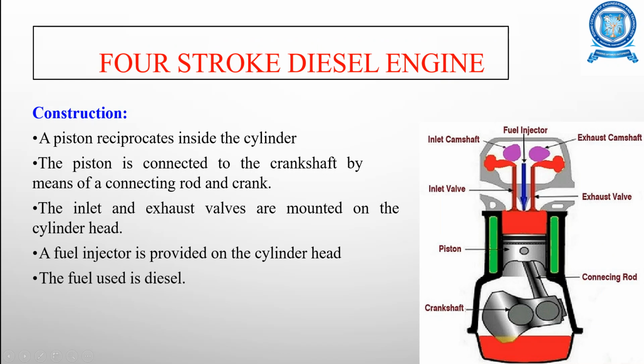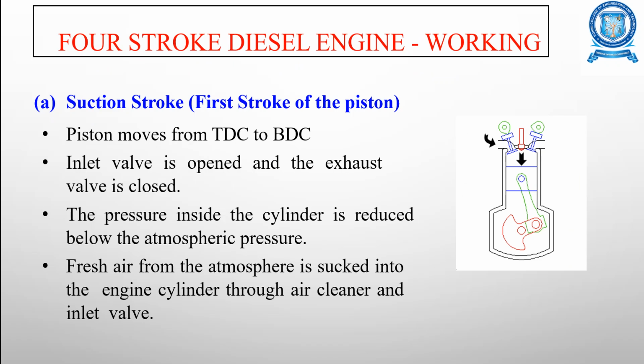In the four-stroke diesel engine, the fuel used is diesel, and this is the first stroke, that is the suction stroke. In the first stroke, the piston moves from the top dead center to the bottom dead center. That is why this arrow is pointed downwards.